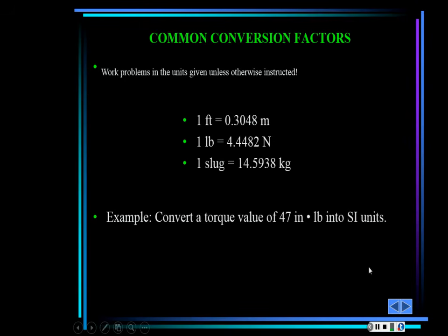No, it's not converting the inches to feet. It's not converting the pounds to kilograms. It's knowing what the units in the SI system are that we have to convert to. So if we have inch-pounds, the first thing we have to know is that in SI units, torque should be newton meter or meter newton. Now we can start. Now we have 47 inch-pounds.